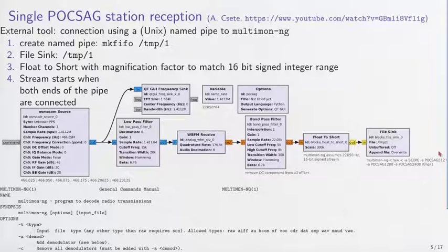So POCSAG is still being used, and we learned by searching on the internet, on the POCSAG Wikipedia webpage, that a few channels have been allocated. These are the channels allocated in France, 466 megahertz up to 466.23 megahertz. We see 6 channels over here, and our objective will be to decode POCSAG on these multiple channels. But before we can address multiple channels, as we have just seen using the FM broadcast example, we need to decode one single POCSAG signal.